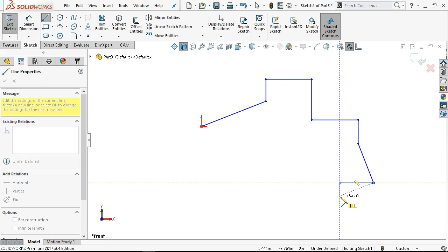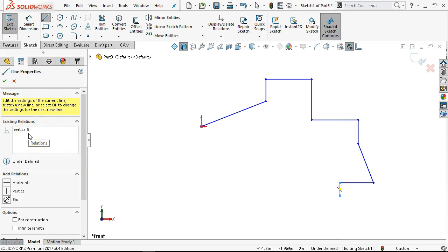The perpendicular is saying that yes, you are perpendicular to that object, but it's in white, so it's more of a reference. It's not an inference. I'm not going to automatically get perpendicular. Vertical kind of takes care of it. Horizontal and vertical imply that I will be perpendicular. It doesn't need to add it as another relation. And then connect the dots.